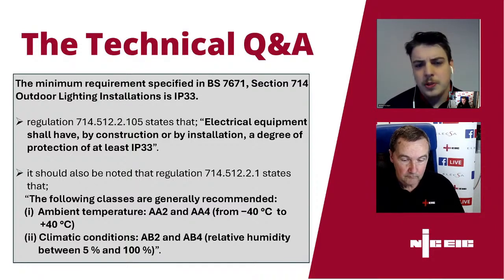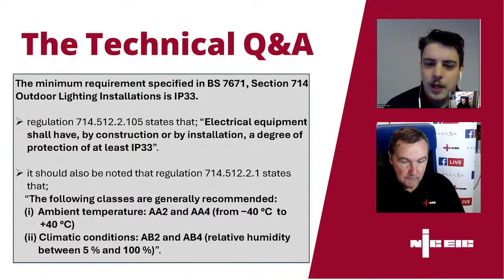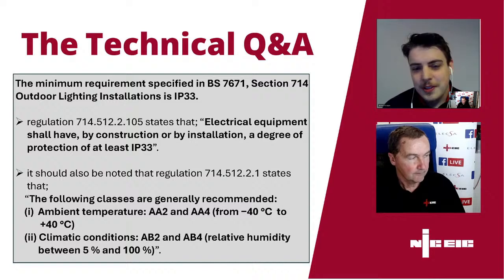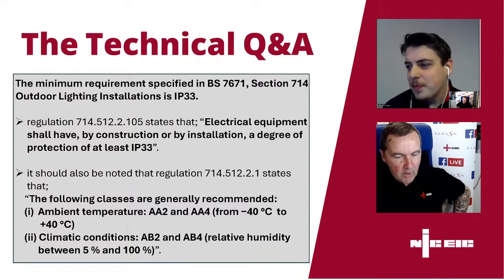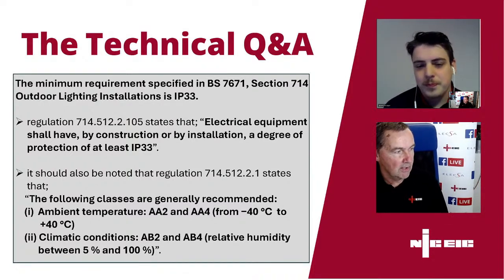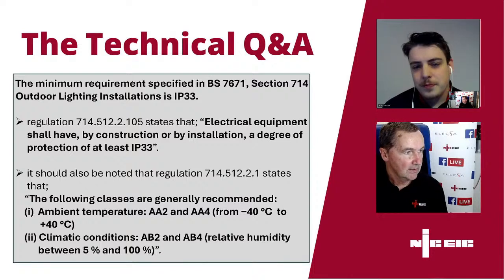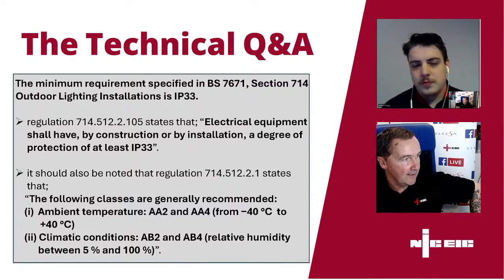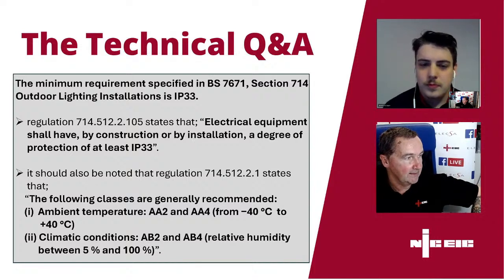I think typically the ×2 value is related to all lines touching at the same time, rather than single fault conditions, but worst case scenario, that's not likely to arise. Even if it were lower, the fact that you're already measuring 4.6 kA on one phase, we would certainly recommend going to 10 kA rather than leaving those at 6 kA.